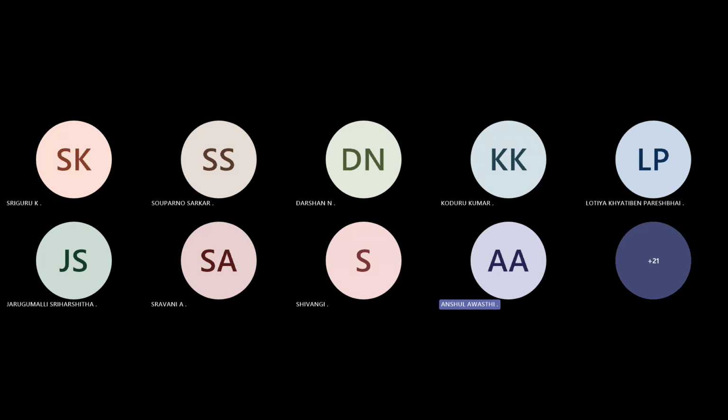That is how the energy band diagram changes with the application of different voltages, and how the electrostatic potential and barrier potential vary inside a diode with different voltages. So this will cover half of our lab portion today. In the later part of the experiment, we'll deal with the single terminal device, that is the MOS capacitor.